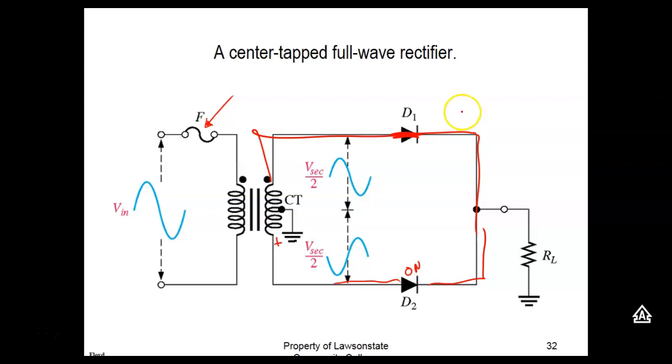But what people don't understand is, if this is a 1 amp load, they think they have to put a 1 amp fuse over here, and that's not true. If it's a step down transformer, so if it's a 2-to-1, then if you put 1 amp over here, your current over here is going to be 1/2 of that, so it'll be 500 milliamps. This confuses some people. They've got a 5 amp supply, and they're fusing it with a 1 amp fuse in the primary.